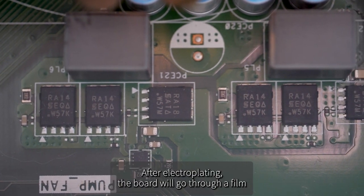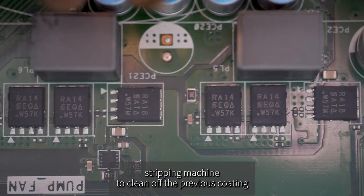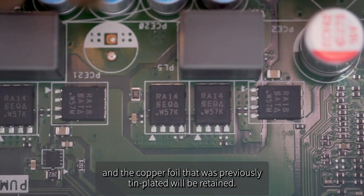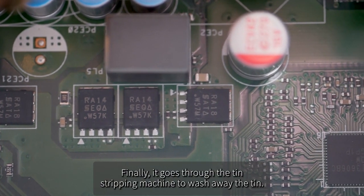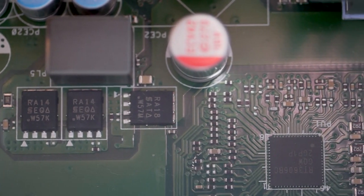After electroplating, the board will go through a film stripping machine to clean off the previous coating, and then the copper foil that does not need to be retained will be etched away, and the copper foil that was previously tin-plated will be retained. Finally, it goes through the tin stripping machine to wash away the tin. What is left is the copper foil we need.